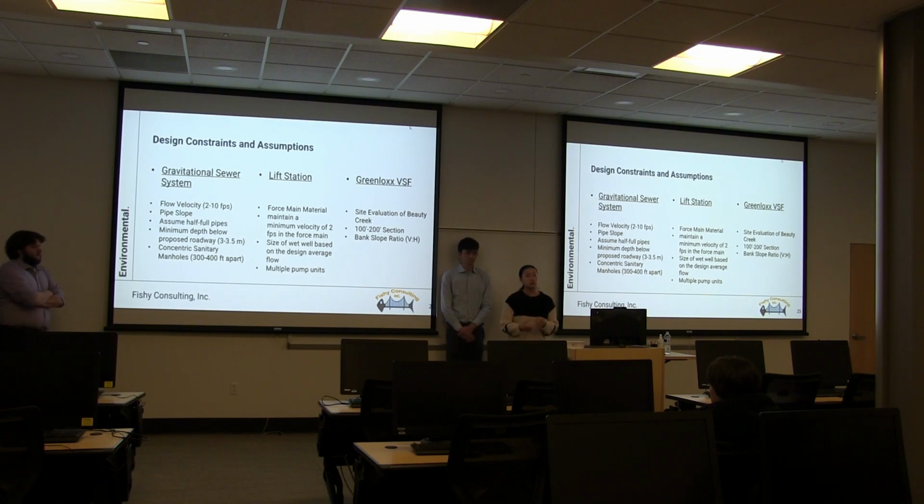I'm assuming that these pipes would be flowing half full because it will help the design handle the peak discharge, while also helping the efficiency of the gravity flow system, and should the subdivision ever expand, it should be able to handle those new expected flows.